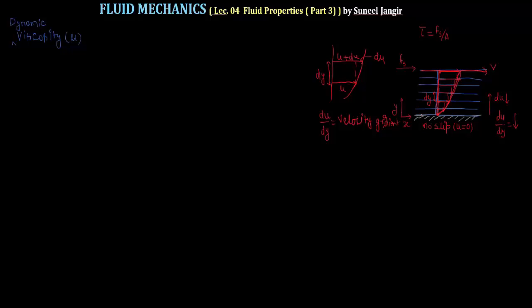If we are talking about the bottommost layer, the shear stress is maximum here, because shear stress is the resisting force, that is the induced force. That's why this layer is not moving, that is the maximum value, because the resistance is maximum here. But as there is a movement here, the value of stress is less. That's why this layer and this layer have some relative velocity.